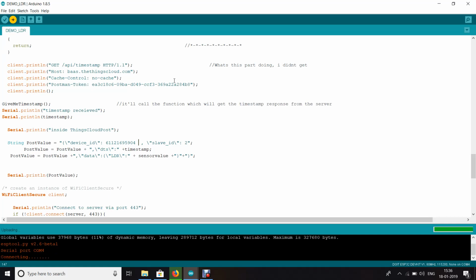The problem with this ESP32 board is, if you want to upload a new program into the board, you have to press the boot button for a certain period of time and then click the enable button. As it has a previously stored program, it will not erase it until we do it manually.